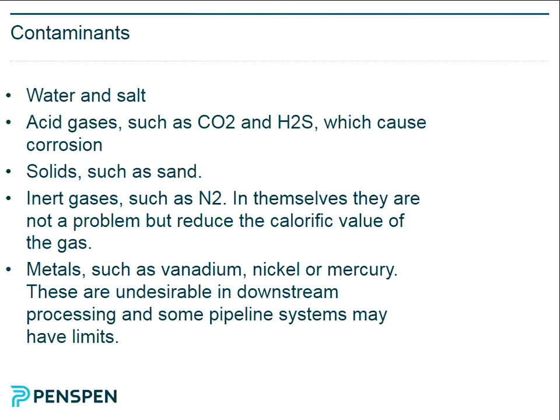And you'll find on some gas plants these things called sand detectors. It uses an acoustic method to detect sand production. Because you might have downhole screens to prevent sand production, but the problem is that they can fail. They can become overpressured. They can actually rupture, and then you get sand being produced from the reservoir, and that could quite quickly damage your equipment, damage chokes, damage elbows, cause failures, create safety issues. So the idea of the sand detector is that once you pick up the production of sand, you'd have to shut that well down and fix it, basically. So it's a safety critical thing, a sand detector.